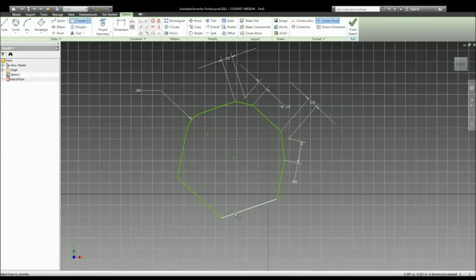So chamfer, 0.125, and then 60. Oh, the angle obviously is going into the shape, so it won't work. Let's do 120 then, which should be the other direction. Nope, still too big. 80? Nope. Messing up on my geometry. I'm so good at this instruction thing. There we go, 25. So 0.125 in, and then 25 degrees from that corner up.